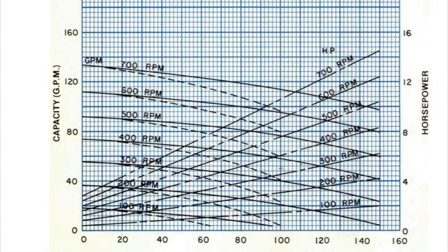It's always important to remember with a progressive cavity pump that you need to bump up in your horsepower rating. We need to bump this up to the next size up, which is going to be the 7.5 horsepower, due to the fact that the starting torque rating on a progressive cavity pump is always going to be higher. So for this particular application, we're going to need the 7.5 horsepower motor. And as we came to the total conclusion, we're at a 2CL10, which is going to give us our 100 PSI, 50 gallons a minute, with our 5,000 centipoise, with the 7.5 horsepower motor.